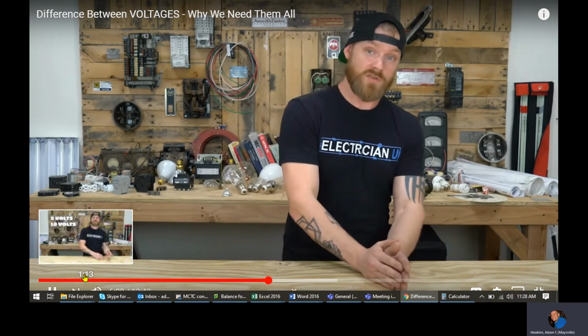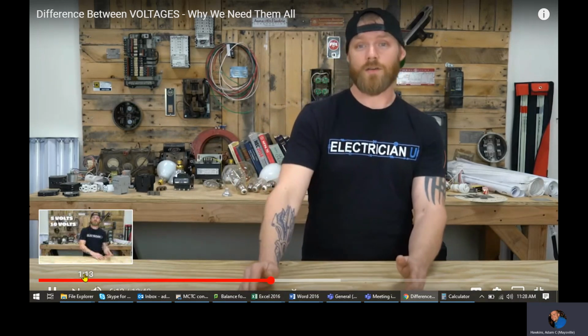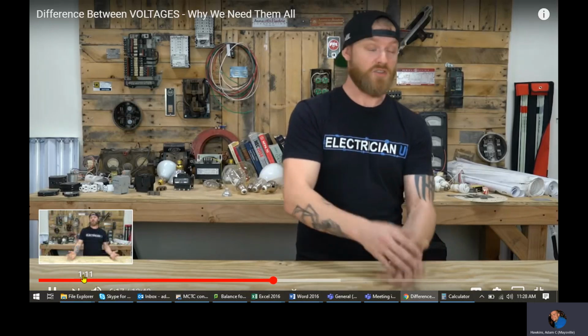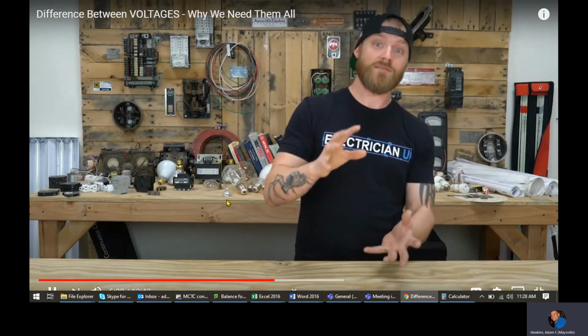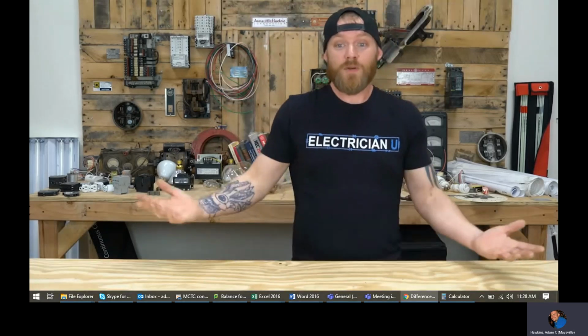There is one other voltage class above that, and that's 347 and 600 volts. So same thing, 347 is just hot to neutral. It's just a really, really super powerful amount of power. And then the 600 is the line to line, hot to hot. But that's pretty much it.